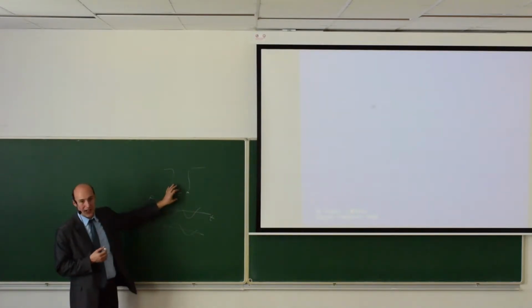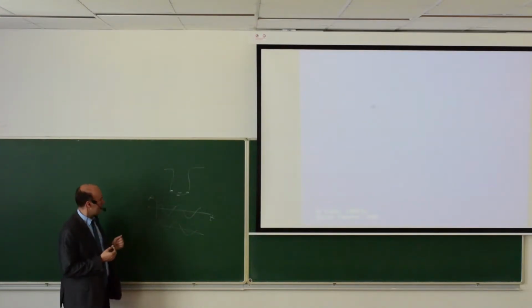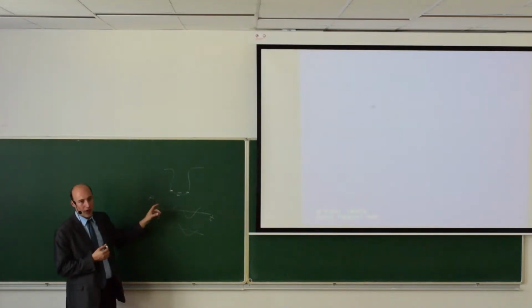Simply because the resonance frequency of this mechanical part will be a function of the density. So the density, or mass, better say mass, of the assembly, but the mass of the assembly will have two parts, the mass of the tube plus the mass of the liquid that is inside.